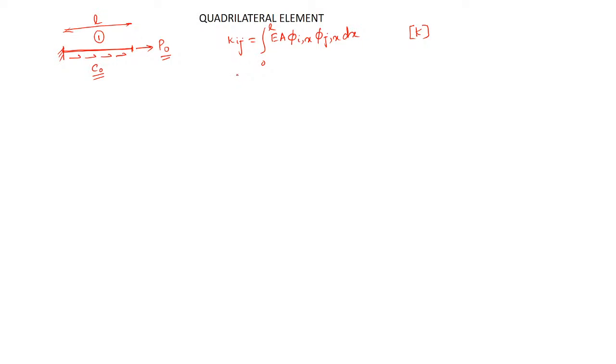Alright, and similarly the force entry in the right hand side that we obtained from the weak form will appear as, in this case, a distributed load, say Fx, and then we will have phi I dx. Fine, and then we will have the Neumann boundary condition, say EAU prime at this, and then we will be having phi I at 0 and L. So this is the right hand side. This part I am not explaining because this has been done so many times.